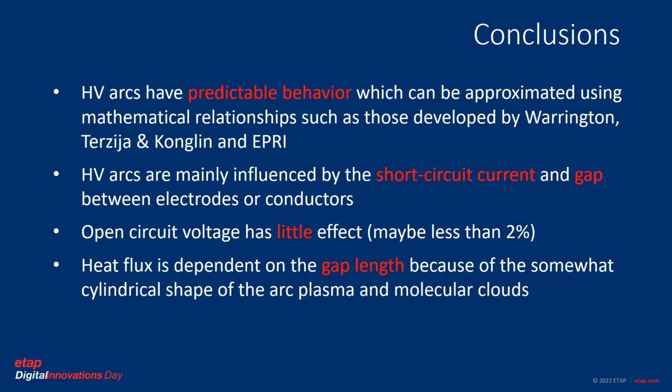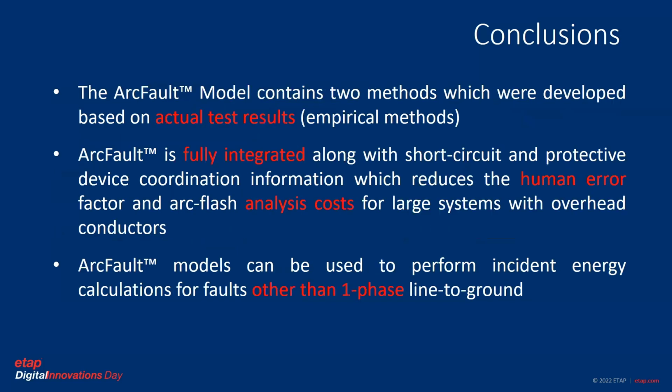And we've also seen that the system voltage has little effect, maybe 2% or less. We also talked about the heat flux and how it showed dependency on the gap length because of the somewhat cylindrical shape of the arc plasma molecular clouds. This is an important concept for us to understand, that the heat transfer model of a long arc is very different from that of more established industrial standards such as IEEE 1584-2018.